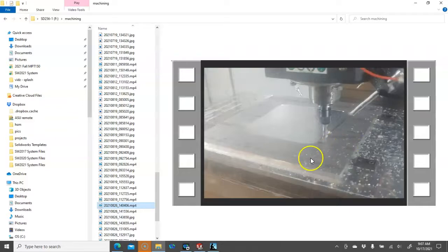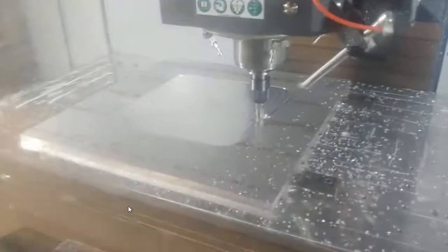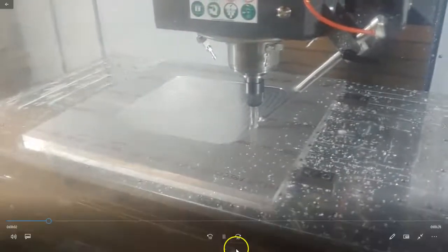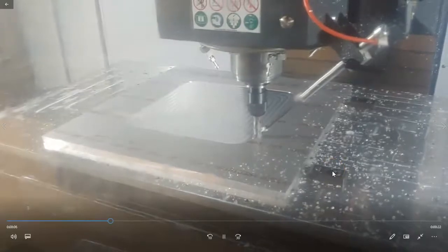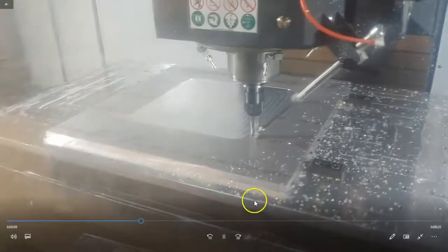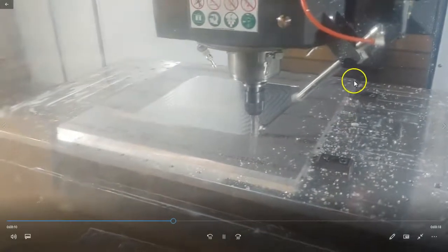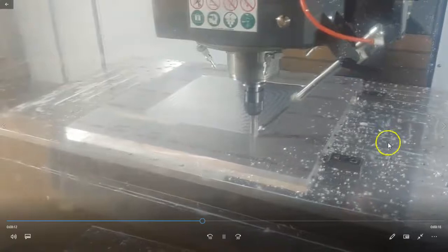So when we go to cut a plate, then we'll get a 3/4 inch plate, for instance. And because of the clamps, the question I get is, why aren't you running the big 5-inch face mill on this? Well, I don't have a lot of room over here and a lot of room over here on the travel of the machine.